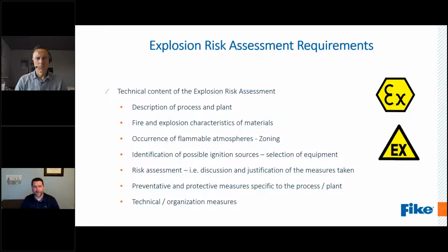It's a very thorough, very well done PHA. It does take a lot of resources and time to do them, but you do get good results if you've got complicated, dangerous flammable gas and liquid situations. You can use a PHA for the combustible dust aspect. I find it's a little more cumbersome just because of the time and constraints on it; there's going to be an easier option than a full PHA, but it is acceptable to be used.